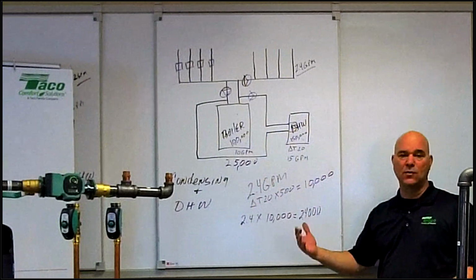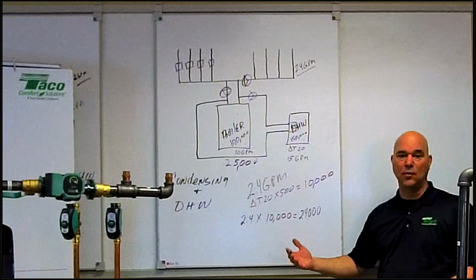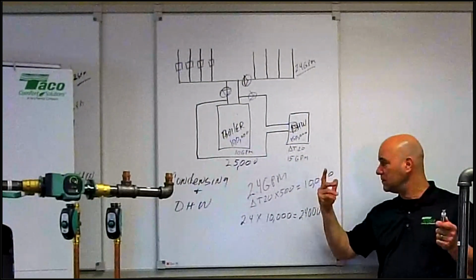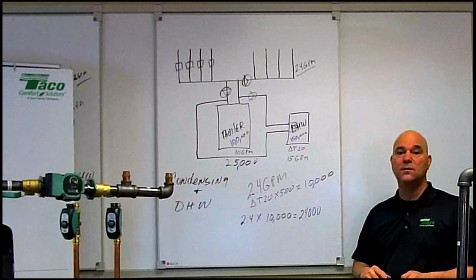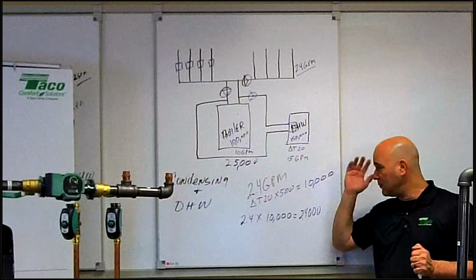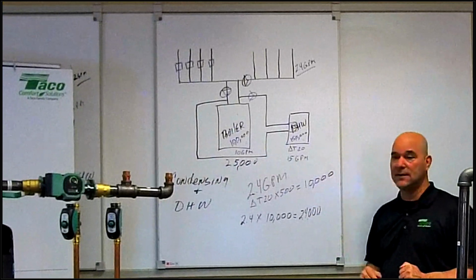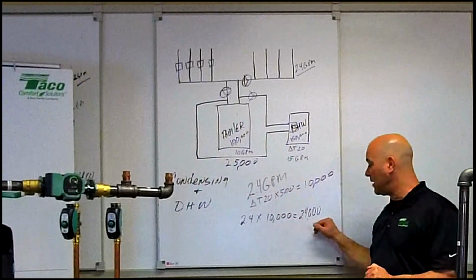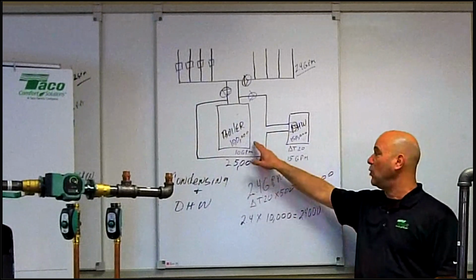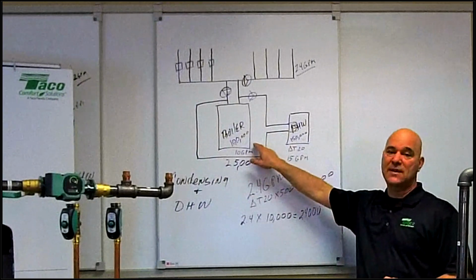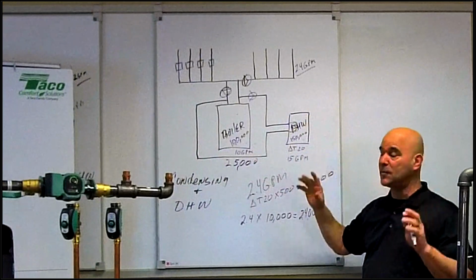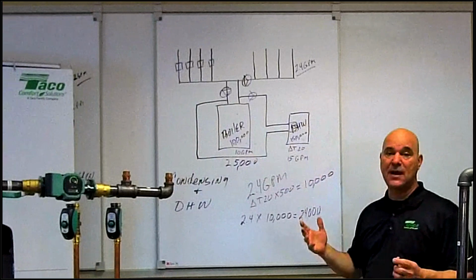So this is why we like the right size condensing modulating boilers. We want them to modulate within their range, 10 to 1, 5 to 1, whatever it is. Our NTI boilers that we offer, we got 10 to 1 turn down rates on them. So we can get down to these lower numbers, but I would not oversize my boiler. I would right size my boiler to handle the load. And usually in our footprint, a lot of times we're sizing for hot water.